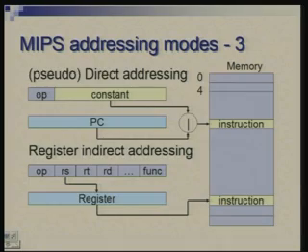So, these are the addressing modes, and you would notice that each mode is applicable to specific instructions. As we will see later, there are cases where specification of mode and specification of instruction opcode can be done in totally independent manner. That means, there are a set of modes, they could be 6 or 8 or 12 or 16, and each mode is applicable with each instruction. So, they are two completely orthogonal parts of the specification, but here that is not the case.